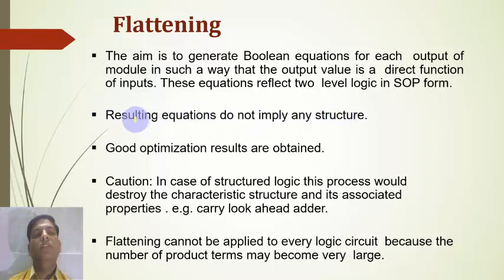Good optimization results are obtained. Caution: in case of structured logic, this process would destroy the characteristic structure and its associated properties. Example, a carry look ahead adder.